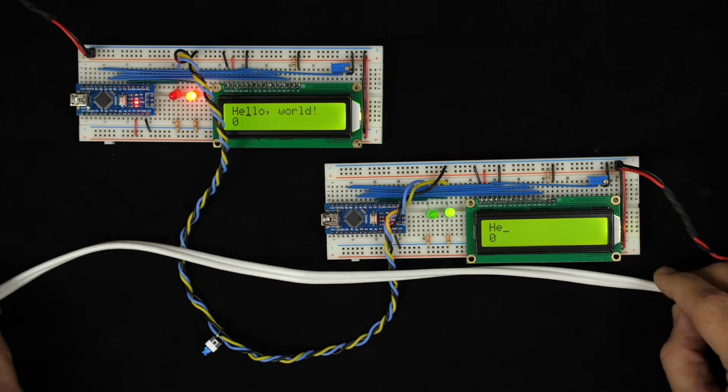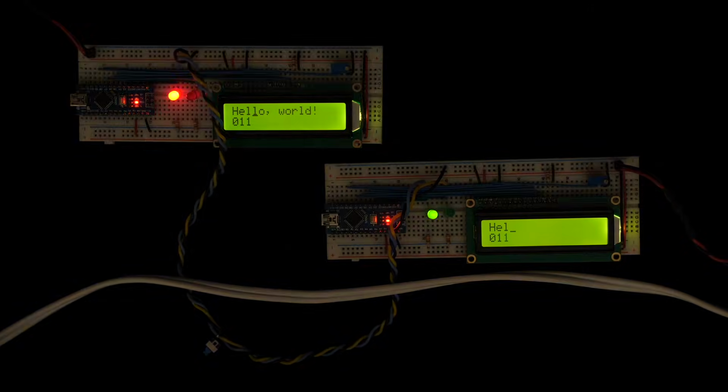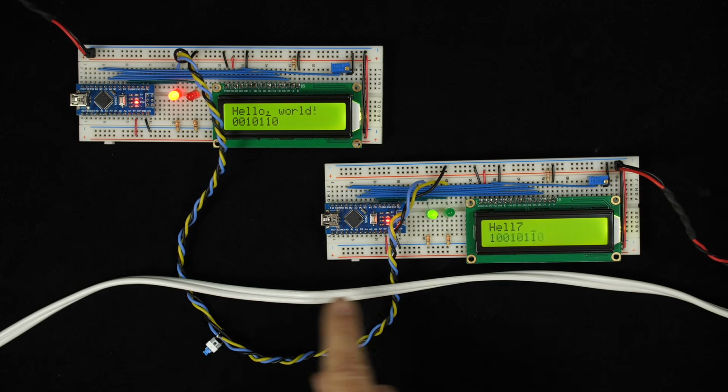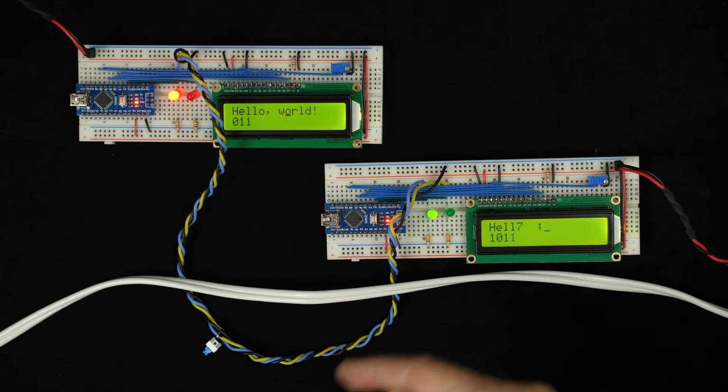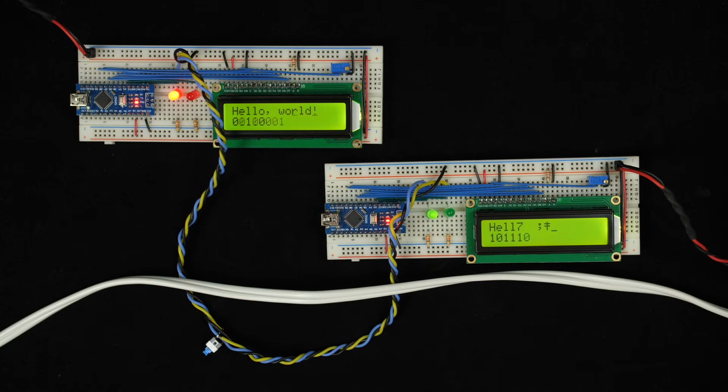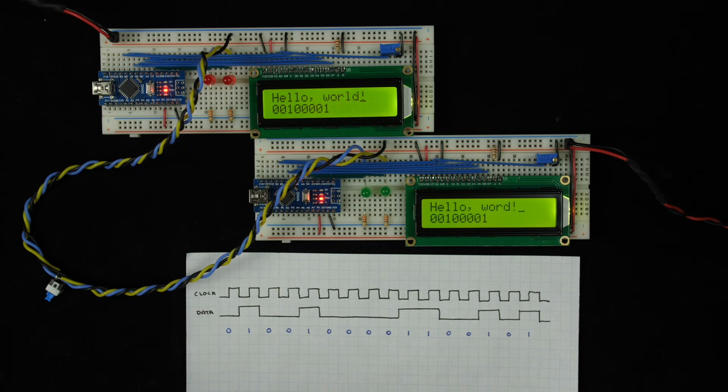For example, if I run the power cord for my lights nearby the circuit, occasionally I can cause problems just by flicking the lights on and off. The quickly changing current in the power cord causes a changing magnetic field that might induce unwanted electrical currents in the nearby electronics. So okay, if we accept that errors are going to happen, what can we do about it?